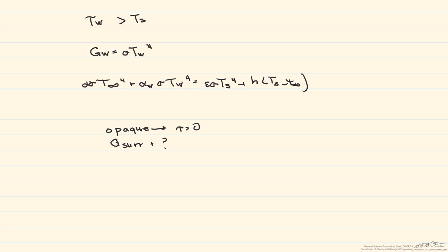Another thing is you might be asked to find this convective heat transfer coefficient, and to do so you may be using a Rayleigh number correlation, or you'll need to find the Nusselt number. So make sure you know the geometry, what type of convection it is, and what the flow regime is.